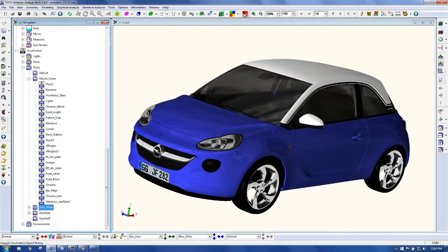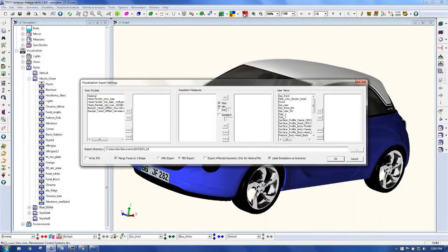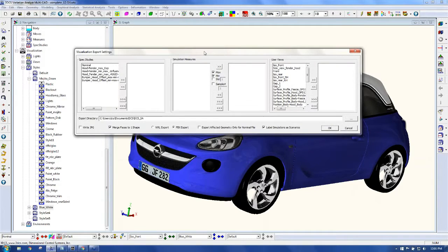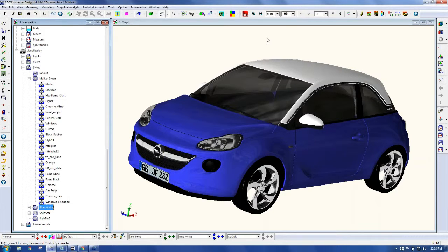So as long as you have the visualization exporter within 3DCS and the importer within DeltaGen, it's pretty much a push button transition. Now, if you don't have that exporter importer, or you're just starting and you haven't decided to purchase anything yet, so you want to try it out, like Scott showed earlier, you can export your nominal build, which will be all 100 parts, right? And then what you do is you just export the specific ones you want to see deviated, and you can start adding those one by one back into it. So you're going to have one nominal set of data, and then you'll have a bunch of sets which are just those parts that are deviated.